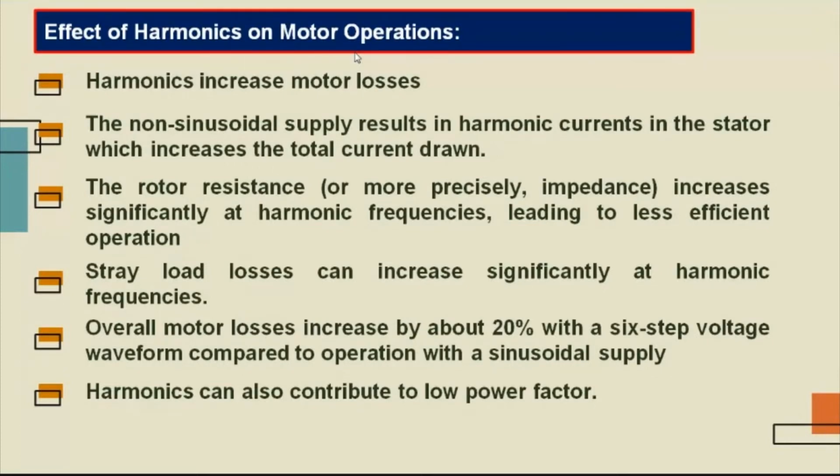So the non-sinusoidal supply results in harmonic total current drawn. So if the total current drawn increases, the energy consumption will increase. Next is the rotor resistance, or more precisely impedance, increases significantly at harmonic frequencies, leading to less efficient operation.